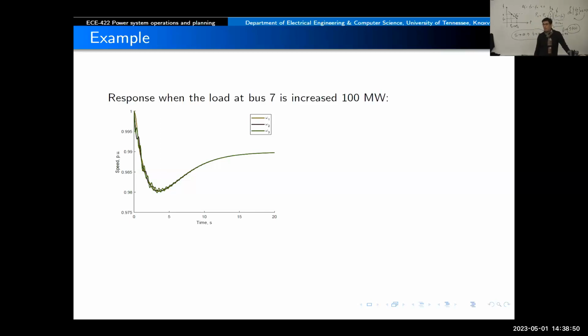Where did that power come from? Because the generators will not be able to change the power output they have, because we have a turbine with some time constant. It will not change instantaneously from the inertia. So that part is going to show almost a linear decay in the frequency, because we're taking that deficit in power from the kinetic energy stored in the rotating mass.